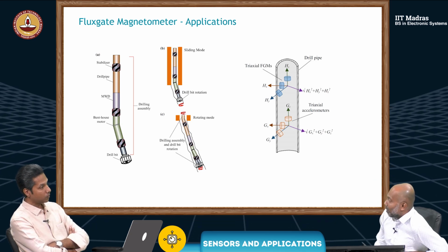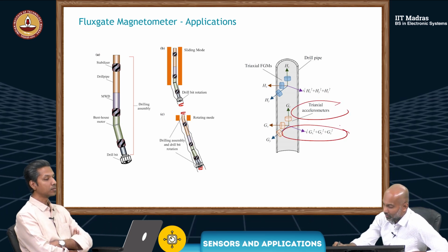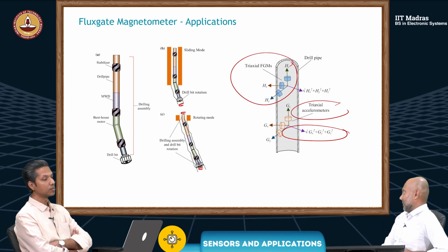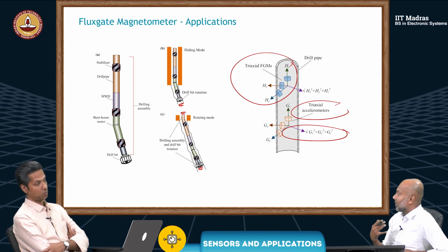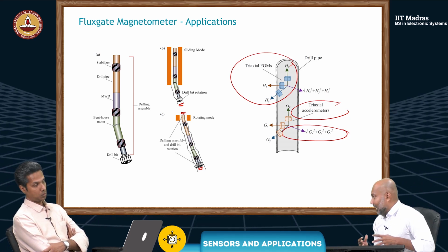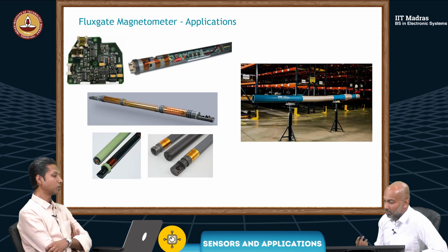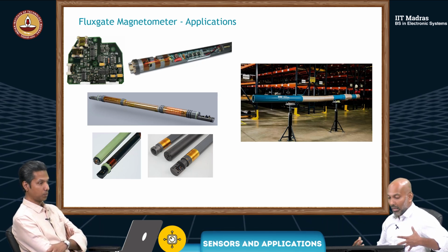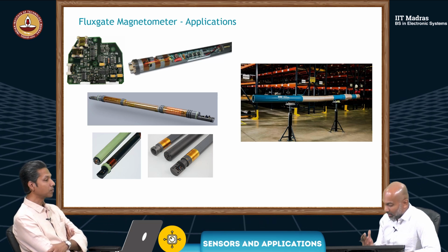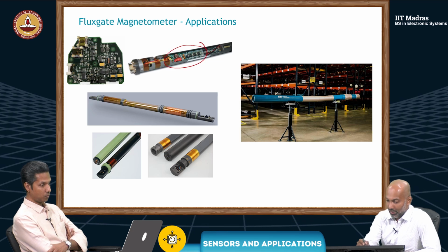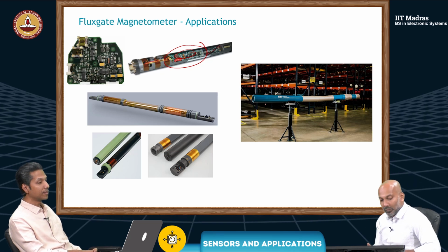What we normally do in this situation is we have accelerometers, but we also have fluxgates. So fluxgate magnetometers are also used when we are performing directional drilling. Now, how do we do this? This is just some pictures of the instrument. Again, it's a little bit like the space boom, but the fluxgates themselves are actually quite small. But you have to integrate them in these big pipes when you're going downhole.